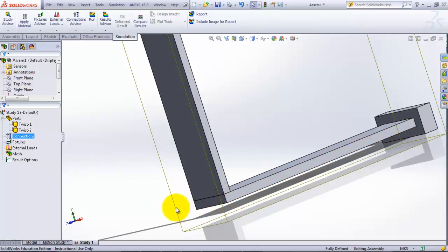You still have to connect. And that's why the global contact is usually just the default. If things are globally bonded to each other, you don't have to worry about declaring it, because the global declaration takes care of all things touching.